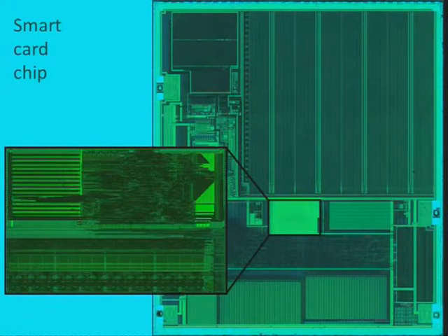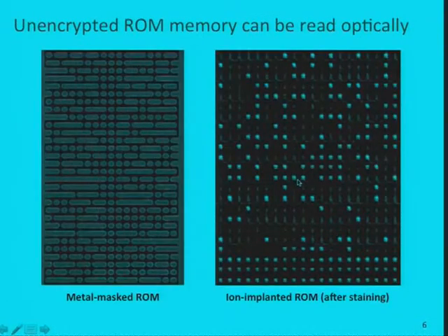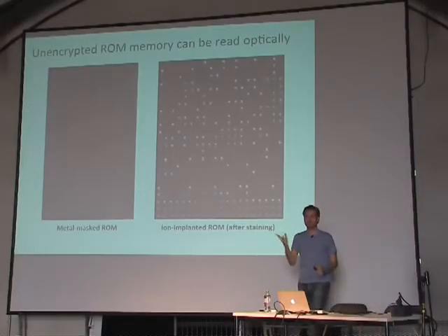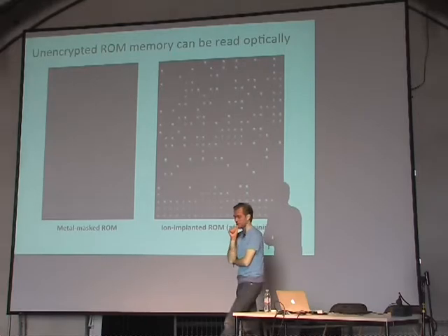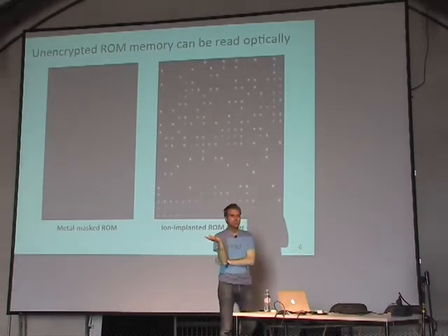its memories. So instead of this pattern of FFFFF that you can optically even see here, this same memory would have a more random pattern, one that doesn't give out the code anymore when put into this newer smart card, right? And that has, for the past 10 years or so, prevented this line of optical readout attacks.